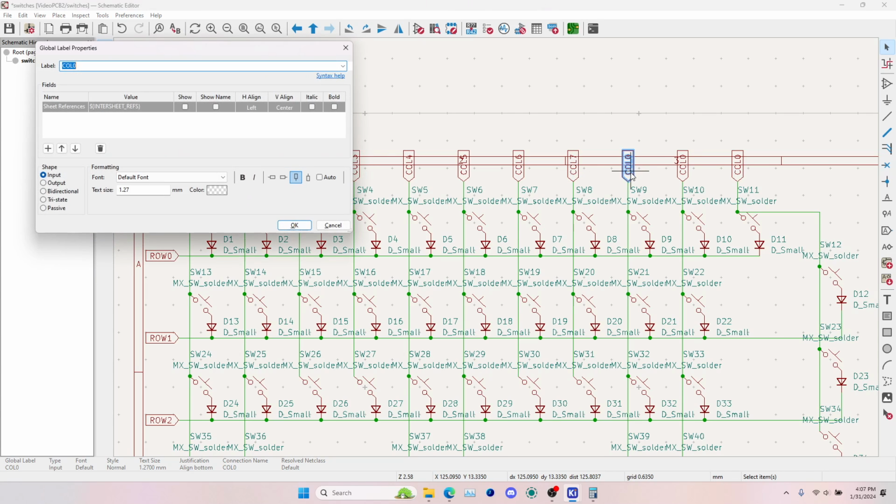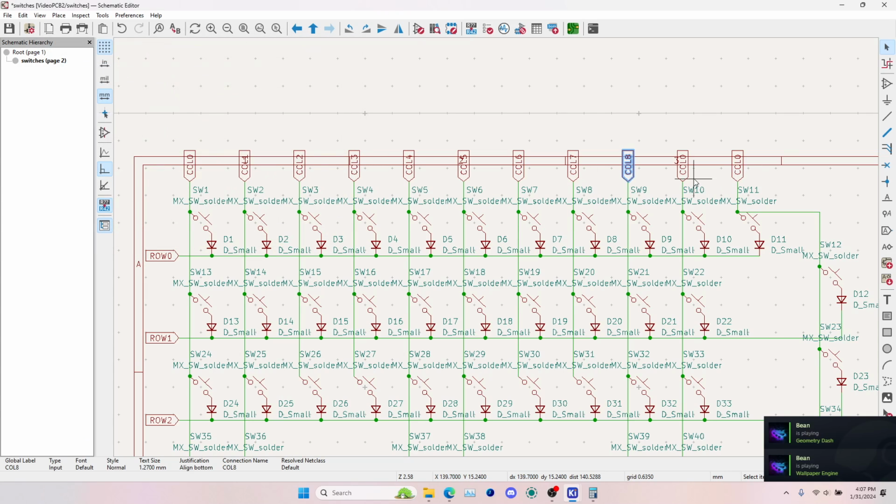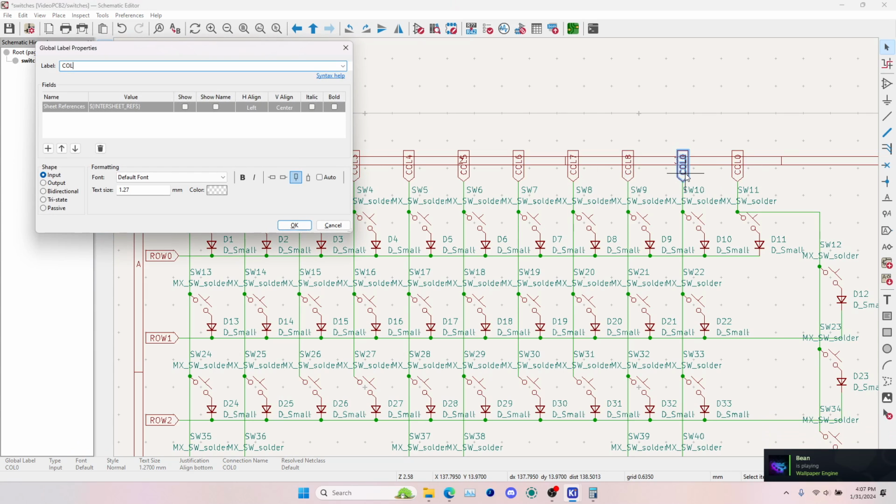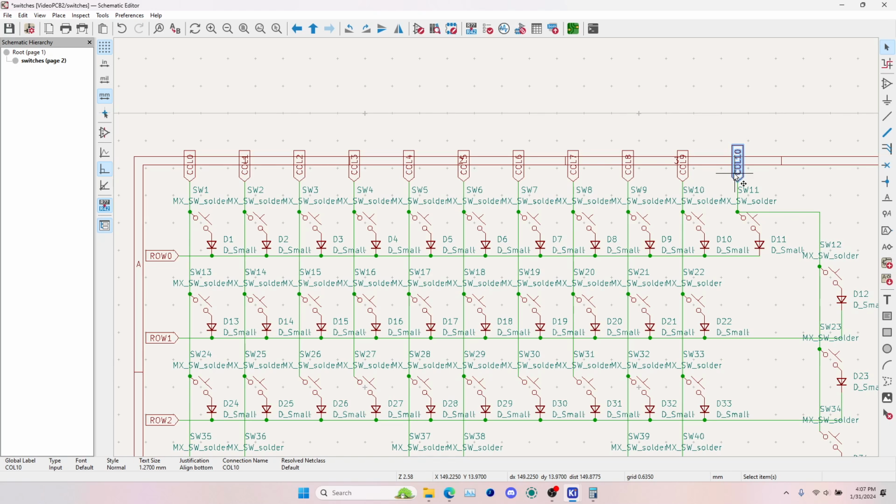Where electrically, well, that's 18 columns and 18 pins, and 5 rows is another 5 pins, and that's 23 pins just for the matrix. That's a lot. Where if you halved that, you'd have 9 columns instead of 18, and you could double the rows if you split it into half.